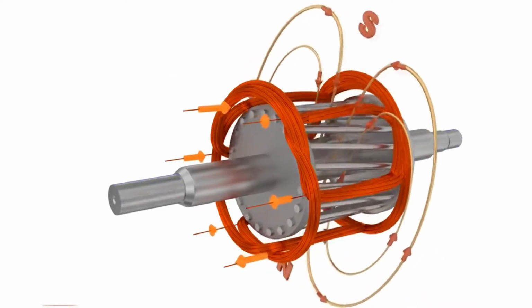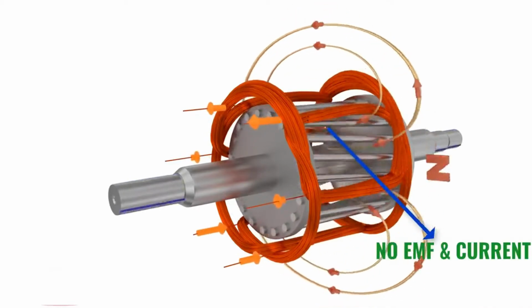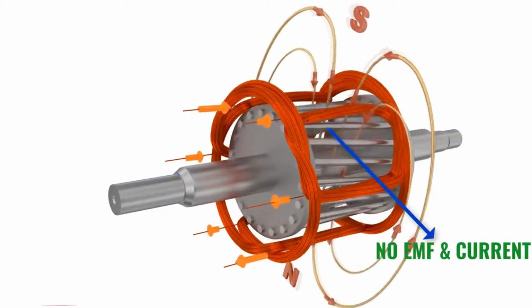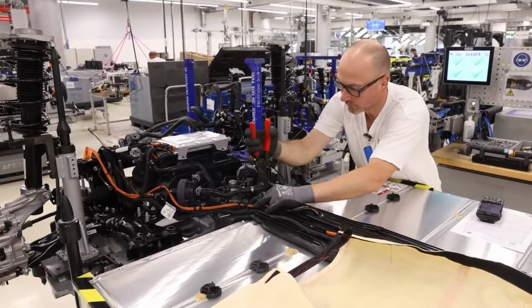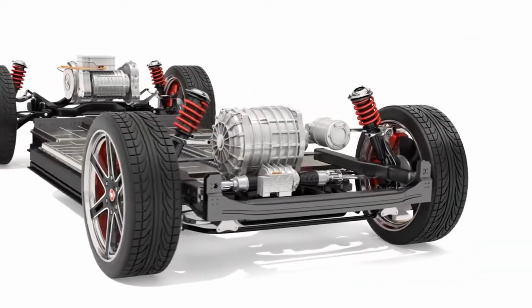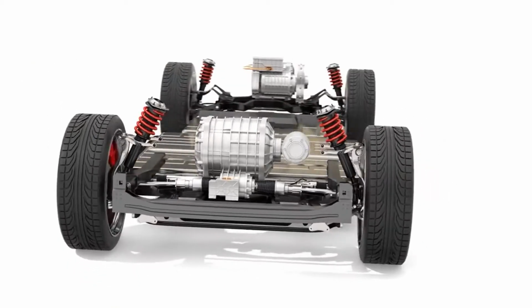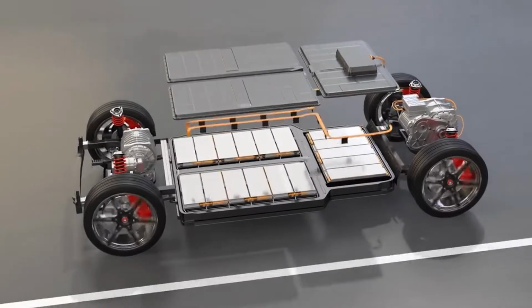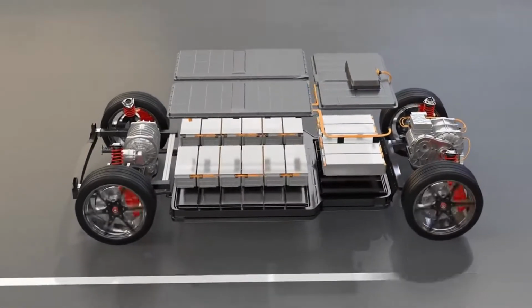In an induction motor, the rotor lags behind the rotating magnetic field speed, or RMF. The motor does not even have a permanent magnet or any brushes either. Despite this, it's very powerful and robust. An induction motor speed depends on the frequency of the AC power supply. If the frequency of the power supply is simply adjusted, the drive wheel speed can be adjusted.